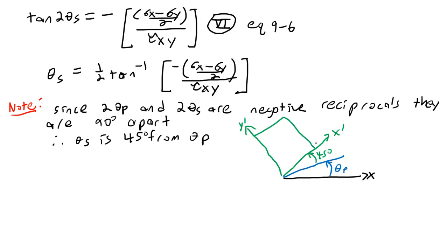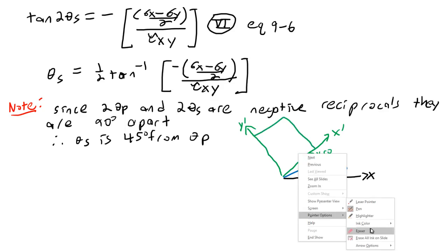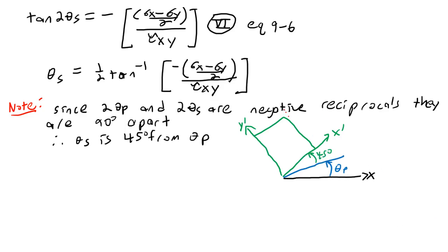And we'll see where sigma average comes from shortly. Let me show in red the actual stresses. So the first thing I'm obviously going to have is tau max, and the same tau max opposite here. And then the normal stresses are all the same value.